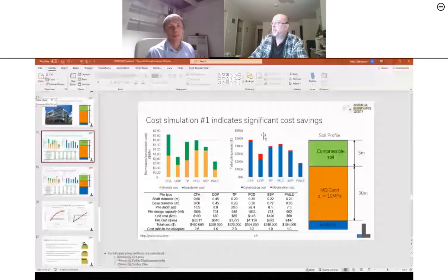And in clay soils, is there a minimum time to wait after pile installation to ensure undrained shear strength gain? Undrained shear strength gain doesn't have to be considered really in the design, and it isn't. It typically isn't when you design drill displacement piles in cohesive soils.